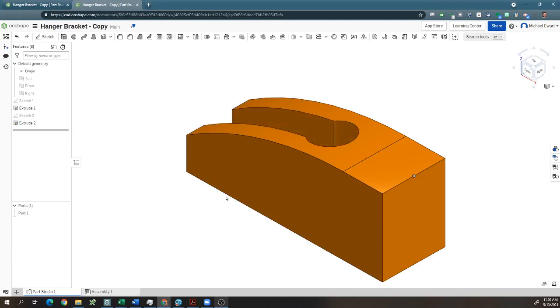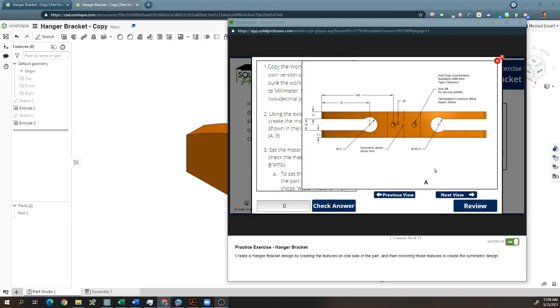So now we have that guy. Next one is going to be to create maybe the hole on top. Since I'm still in the top view, this hole. And so this is a point that's 20 away from the top, 109 away from the right.